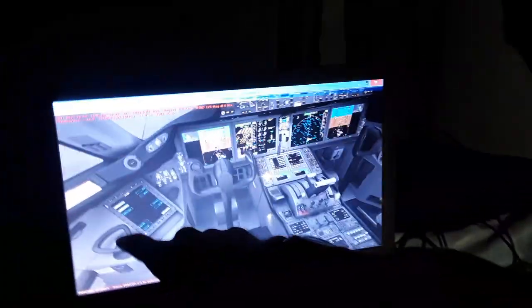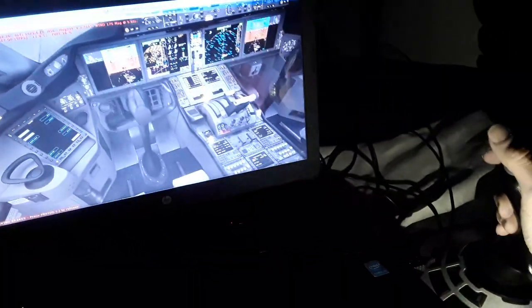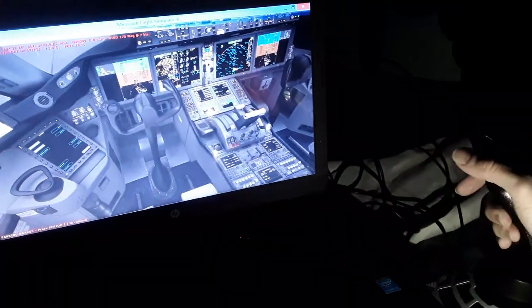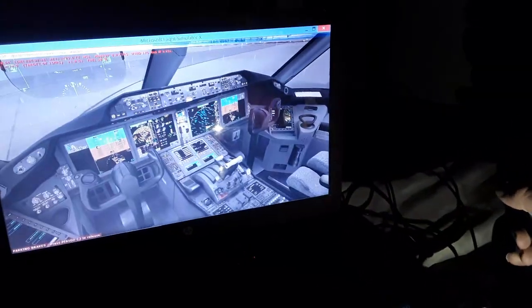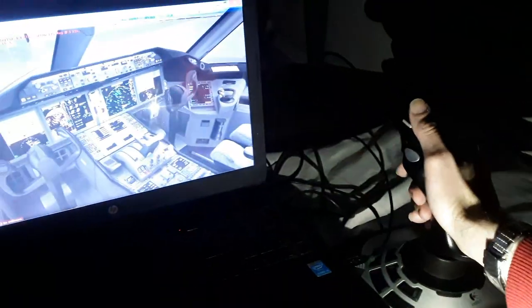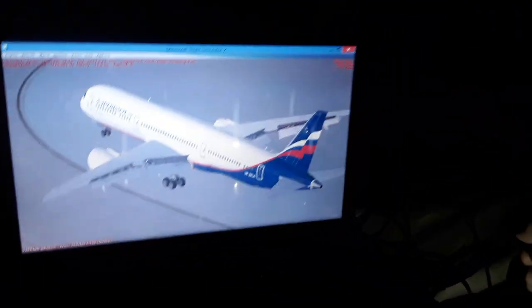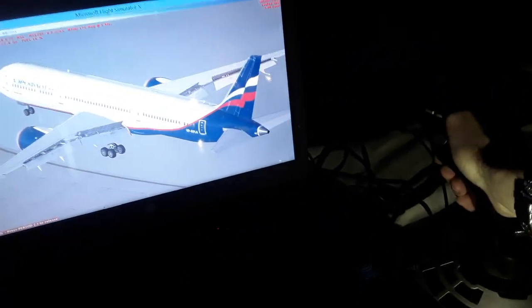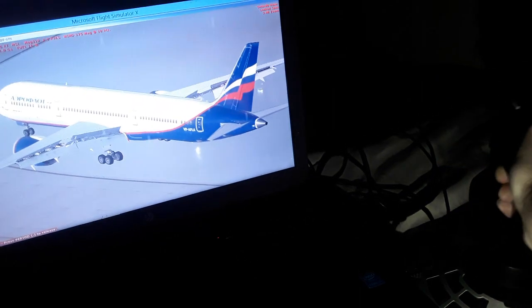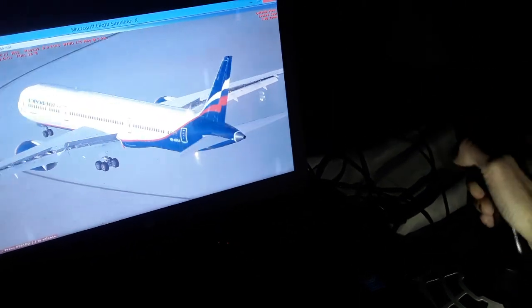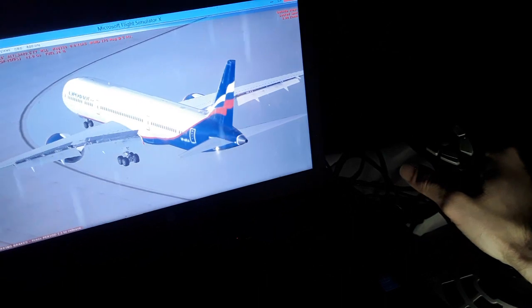So we have also interconnected the tiller over here and the rudder pedals. So I will show you all these things, the flight controls, how we control the horizontal elevator here for climb and descent, make turns left and right over here, bank rolls left and right.